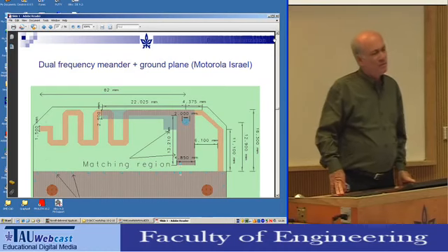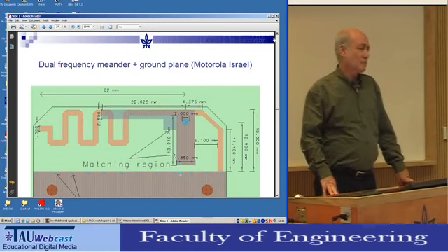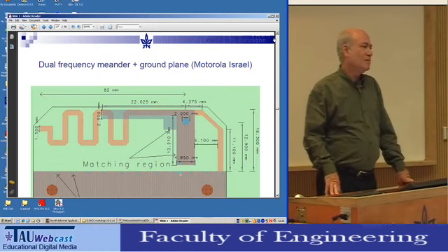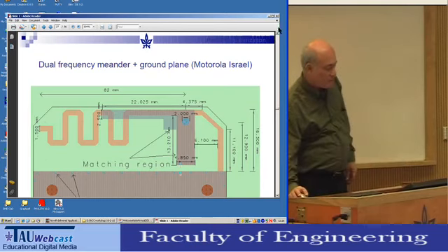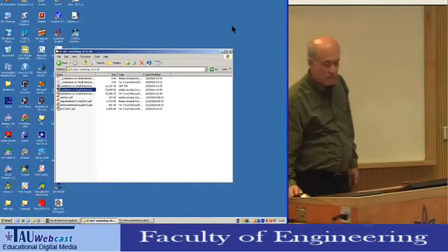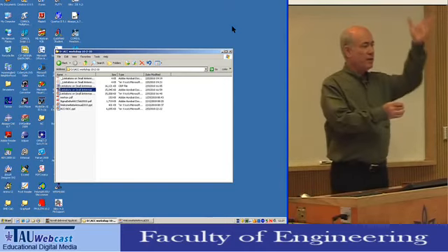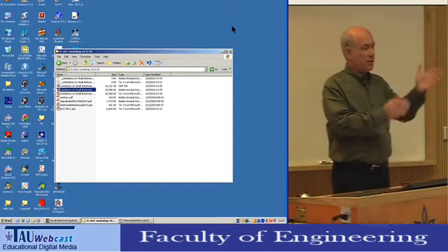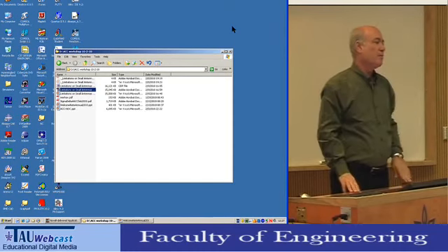I know that sometimes when somebody stands near the antenna, or there is something near the antenna, it can influence the performance on the positive side. If you knew that the antenna is near some metal body, would that significantly change the picture? Well, it's like you take a half wavelength dipole and put it next to a conducting screen, which is a ground plane, at a quarter wavelength away, and it will enhance the radiation in the other direction.